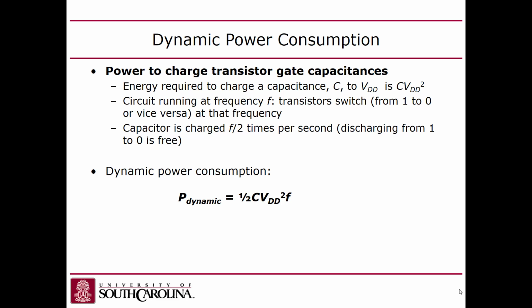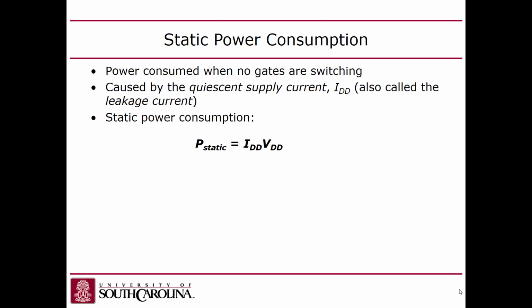All right, static power consumption. In the old days, it wasn't a very significant amount of power because when you turn off a CMOS gate, it has high impedance, right? But the problem is that we're lowering the voltage and we're getting closer to the threshold. And so the effective impedance of the CMOS transistors is less than it once was because we're lowering that VDD.